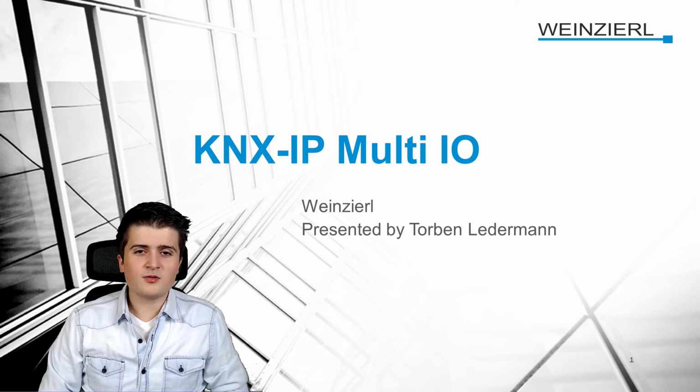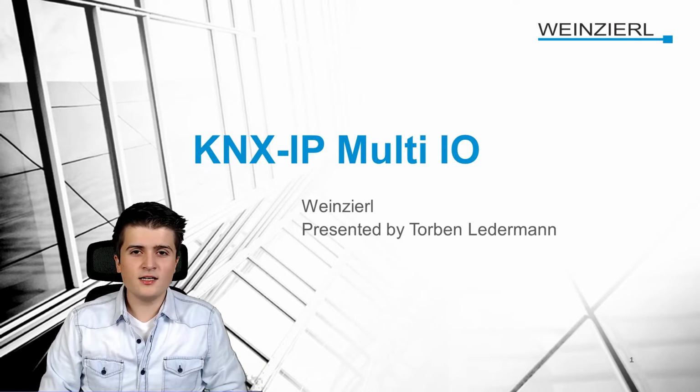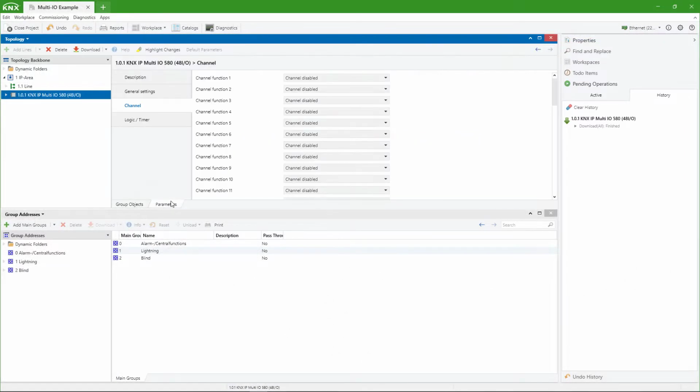In this video, we will see how we can use the multi-I/O in combination with the extension module 590 to use it as a switching actuator. To enable the switching output for the KNX IP multi-I/O, we first have to go to parameters, and there under channel we can specify the channel functions. The first channel function is in my case the switching actuator, so the extension module 590.